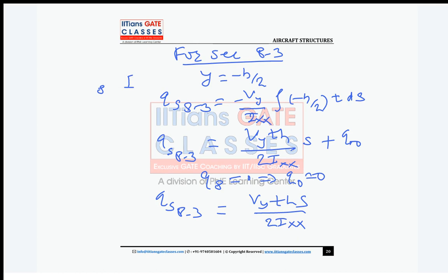Now guys, I want the shear center position. So what do I do? I'll take the moment equivalence about this point, right? And I can use symmetry. Why am I not taking about point 5? Can anybody tell? Because if you take about point 5, you will require additional shear flows, right? 1 to 2, then 8 to 3, and then 7 to this also. So that means we can use symmetry here, and we will take the middle point.